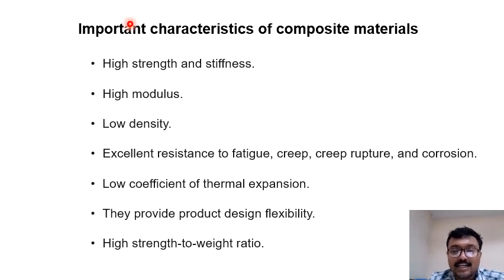The important characteristics of composite materials: high strength and stiffness, high modulus, low density, excellent resistance to fatigue, creep, creep rupture, and corrosion, and a low coefficient of thermal expansion. They provide product design flexibility and a high strength to weight ratio.